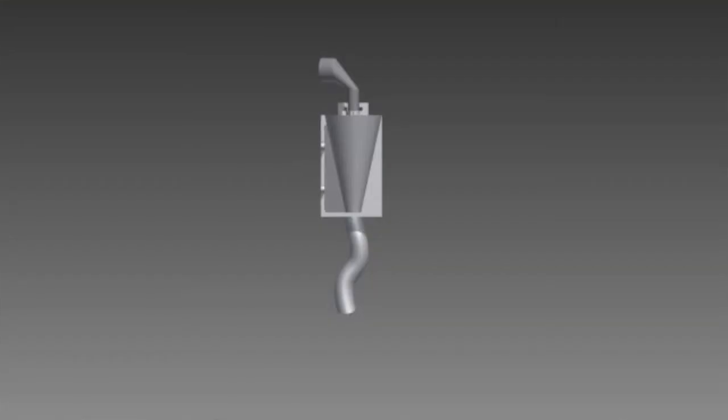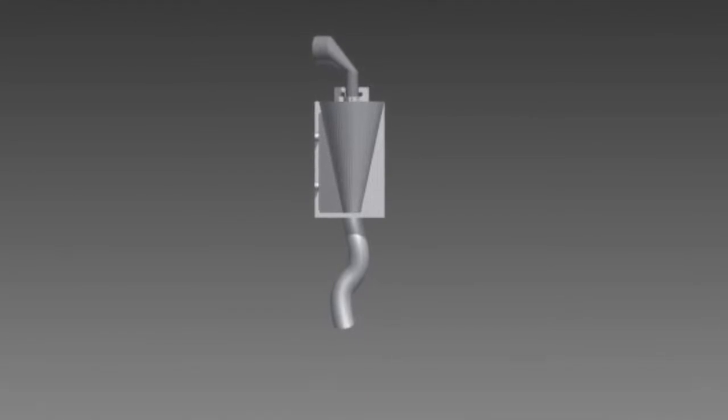One of the main parts I was responsible for was the air intake. The old design was a box filter which consumes much less air than the cone filter. I redesigned a cold air intake with the cone filter and added a heat shield. The cone filter allows much more air to be filtered through the system, resulting in better fuel consumption for the overall system. The heat shield ensures that the cold air is always cold and the engine does not heat up all the air that's being fueled into the system. With this new modification, the car is much more fuel efficient, and on top of it all, it adds a little more power to the system.